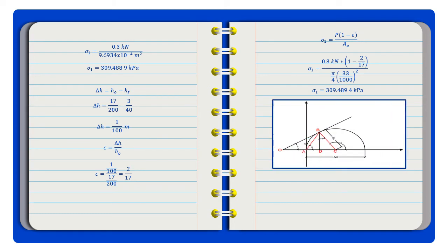So, first, kunin natin yung Mohr circle. Pa-plot kasi natin dito yung nakuha nating sigma 1 or yung delta sigma. So, since this is an unconfined compression test, syempre, yung plot natin is magsa-start on the 0, 0 coordinate. Siya kasi yung minimum principal stress. Then, adding the deviator stress will give you the sigma 1. So, this means that this sigma 1 is also our delta sigma kasi equal lines lang sila.